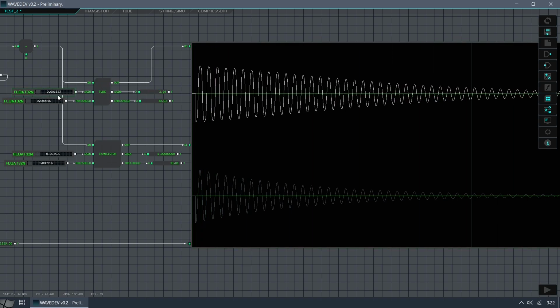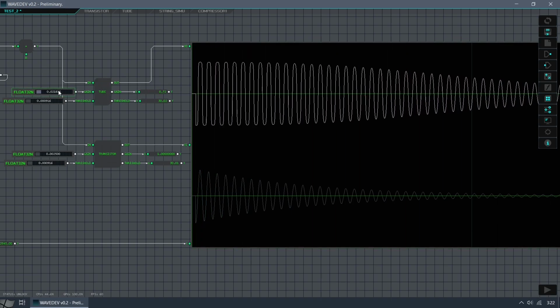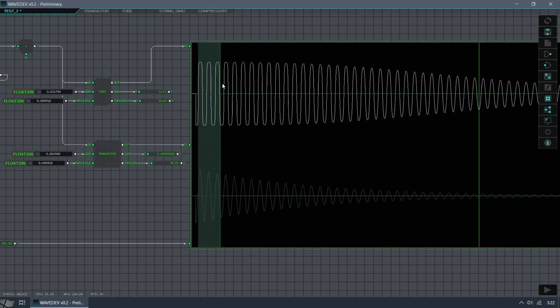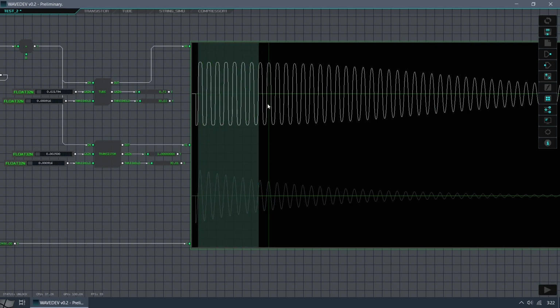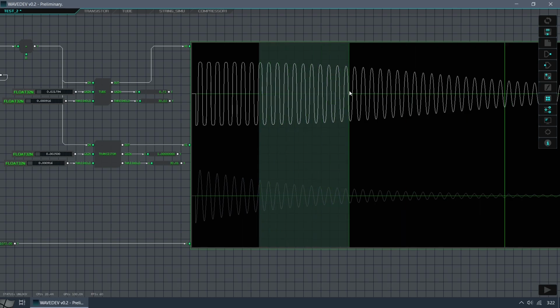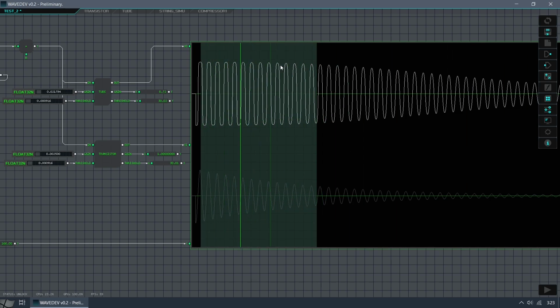So, the saturation itself causes this compression effect. While the first oscillations are clipped or compressed, the gain also lifts the oscillations below the threshold. So the decay of the signal is no longer exponential but rather flat. This allows all notes on the guitar to sound with the same intensity. And it is the main difference between the sound of a distorted guitar and that of a clean guitar. In the same way that we filter and normalize the components that must be saturated, I consider this type of compression as the normalization of the amplitude.